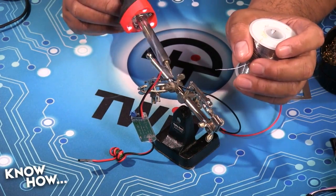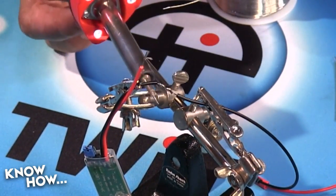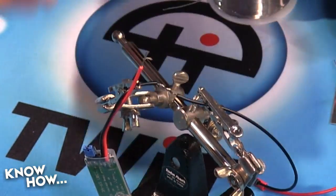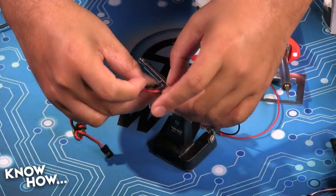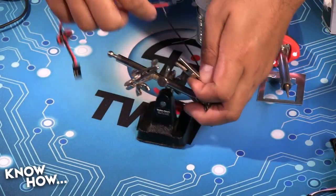Precisely. But if you're having trouble making that happen, you can put a little dab of solder onto the tip of the iron, and it acts like a heat bridge that will conduct the heat back into whatever you're trying to solder. If you're having to melt the solder on the tip and then put that on the wire, that probably means you need a new tip, though.